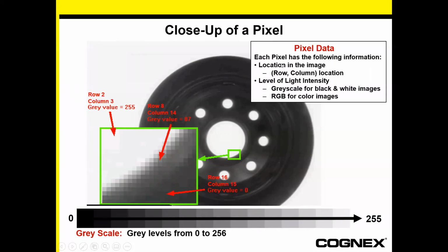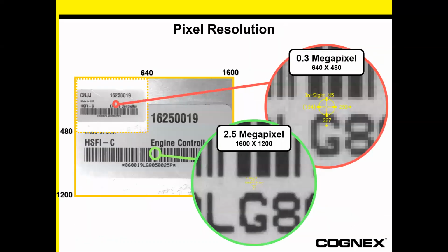Now, this is a mono camera. Most, I'd say 70% of cameras we sell would be mono or grayscale for applications. The rest would be colour nowadays. In the past, colour and grayscale cameras, the colour ones were more expensive. Nowadays, same price. It's just really a matter of what's right for your particular application. What you got to remember with a colour camera is you have X, Y, and then you have RGB. So you have a lot more information, and with that, processing time is slower. Something to keep in mind.